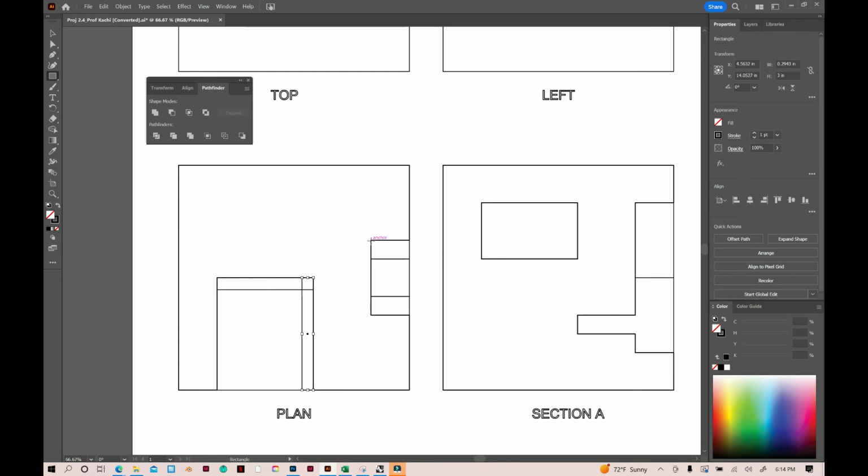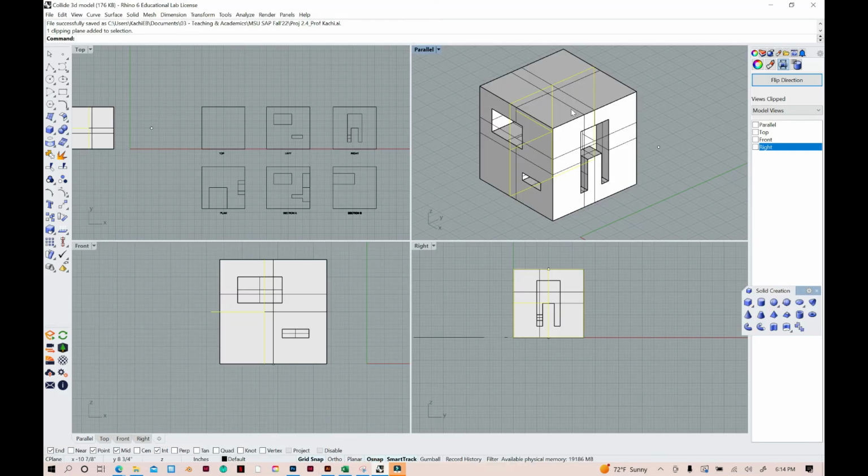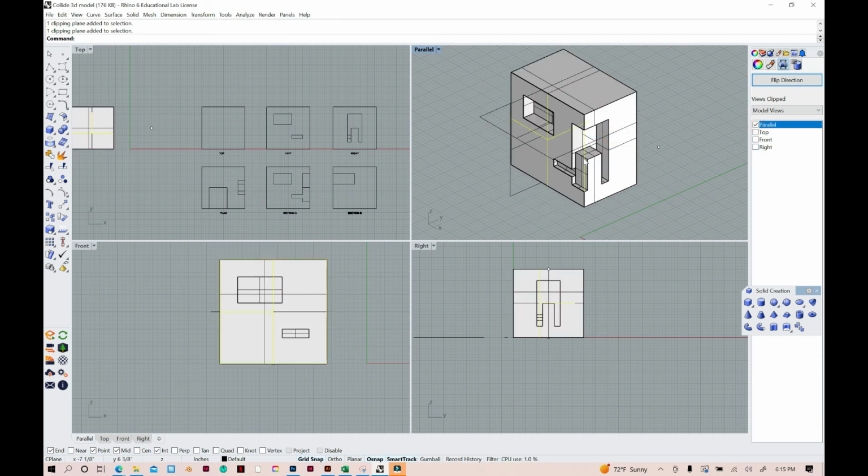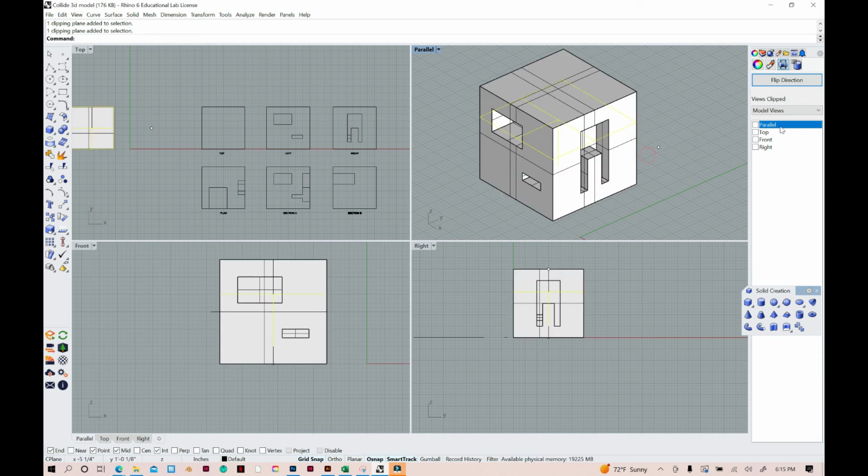So same thing here, you would have a shadow here. Oops, mess up, Control Z, your best friend. But you would also have a shadow here, because if we refer back to my Rhino file, and this is the best thing to do, if you turn on your clipping plane and turn it back on parallel, you can start seeing where different things are happening. So this is the wrong clipping plane, so we're gonna turn that off and click on the one I actually want. I want this one. So you can start seeing there'll be a shadow here, but there would also be a shadow down here.